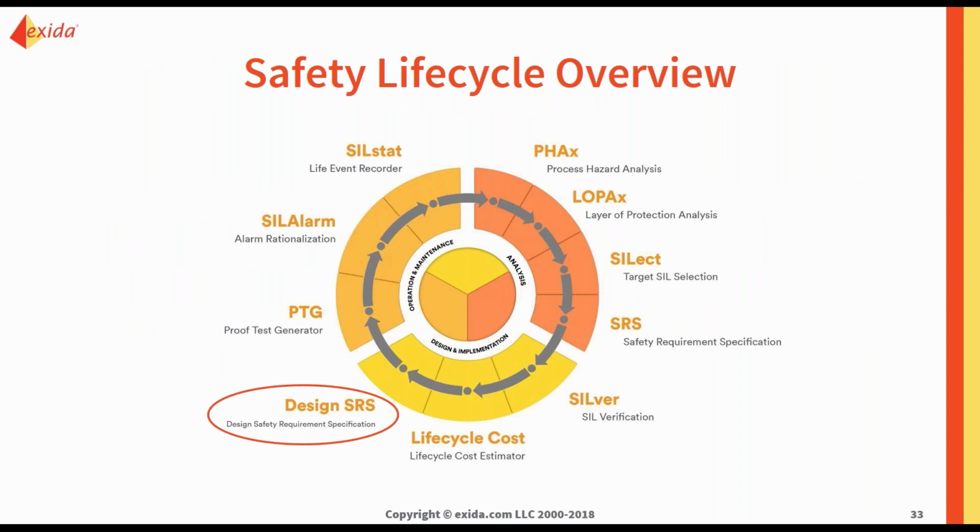So if we go back to our lifecycle, we see the Design SRS is here at the end of the design and implementation stage. So you have your SIL verification, you might weigh your costs when it comes to equipment, redundancy, proof test strategies, any routine maintenance, and then hopefully your conceptual design is set and you're going to communicate that out using the Design SRS.